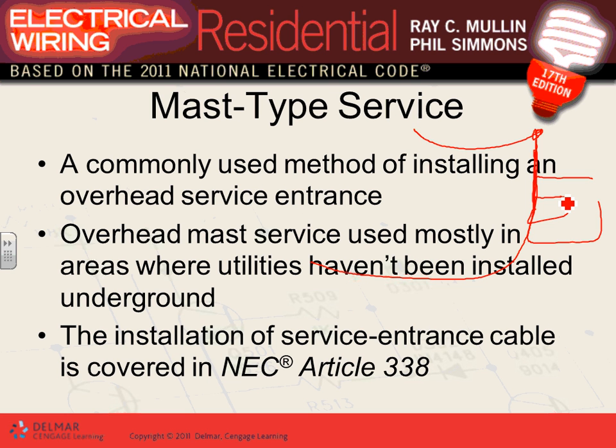Can I get you guys to understand the terms that the utilities use to describe the power lines: service drop if they're overhead, or service lateral if they're underground. That's it. These are their conductors. Our conductor that is tied to their conductor, we call the service entrance conductor, because it brings the service into my building. In between the service entrance conductor and the service drop, there might be service conductors if the service is big.